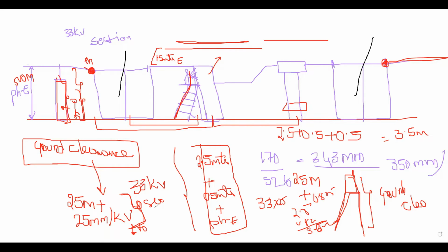Again, the calculation is simple. It's the same calculation. By knowing the ground clearance, the sectional clearance, the face-to-face clearance, and the phase-to-ground clearance, I can prepare a layout. Again, this is subject to the utility standards and the structure design you have for that project.